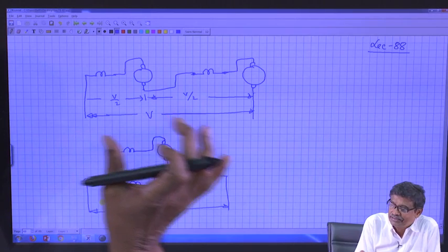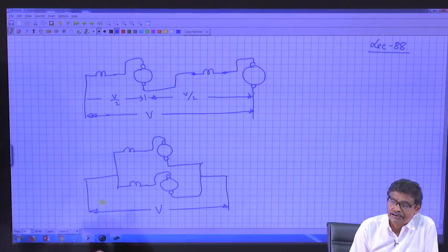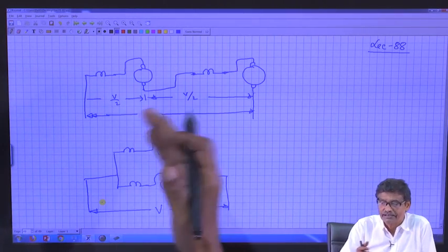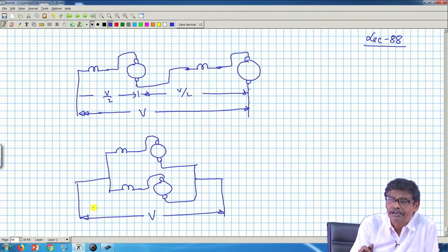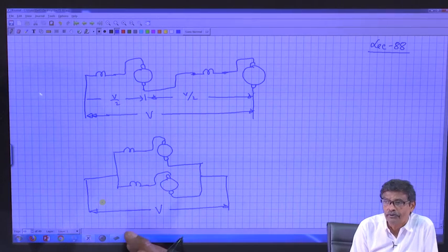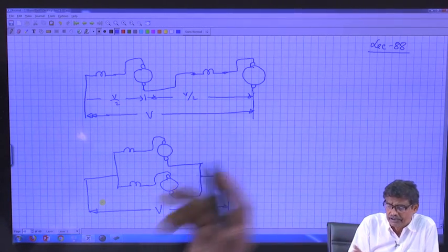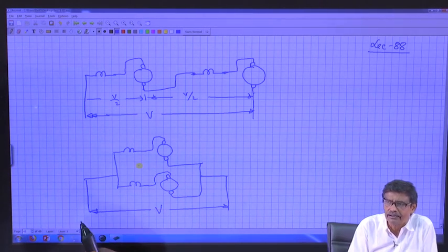You connect them in series, then as we have just indicated for a motor, if you reduce the voltage by a certain amount for the same load current, you can calculate the speeds, and similarly you can connect them in parallel and get another speed. On top of it, if you want to run at higher speed, then the individual field coils can be connected in series or parallel.